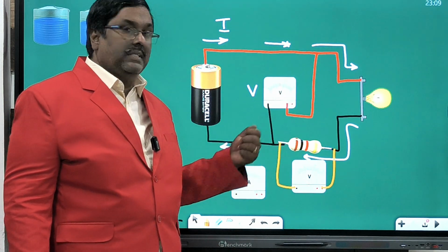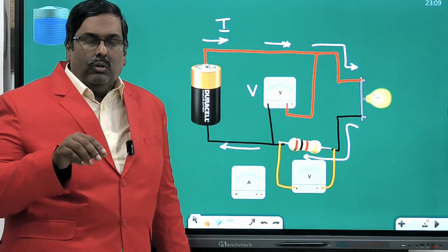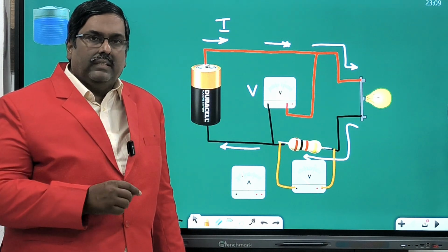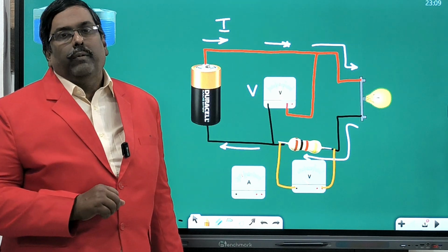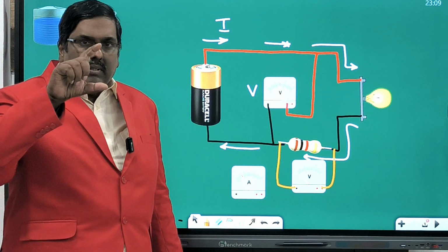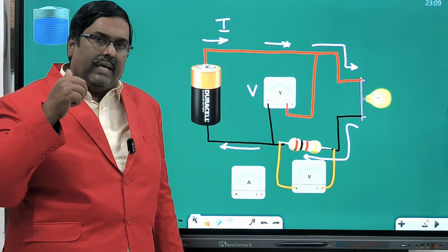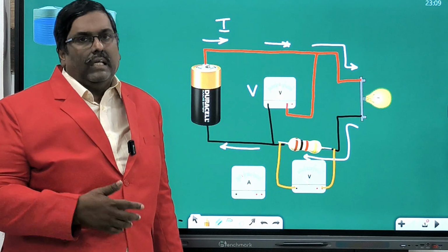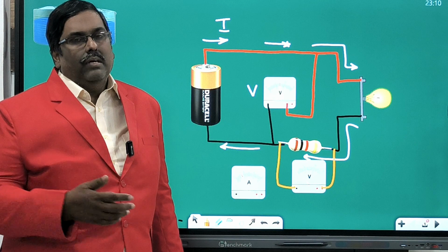Some places you see in marine panel boards, instead of using a resistor, they use a metal plate. The metal plate also has some micro ohms. So they put a voltmeter in parallel, and take the voltage as a reference for the alarm. If there is more current, that means more voltage, then the alarm will rise.